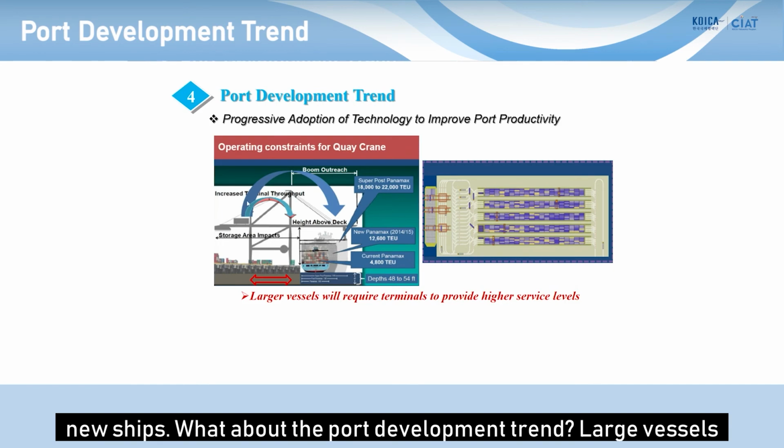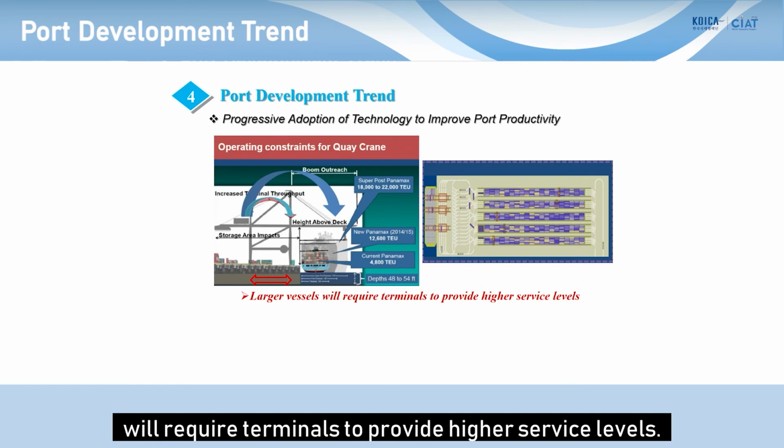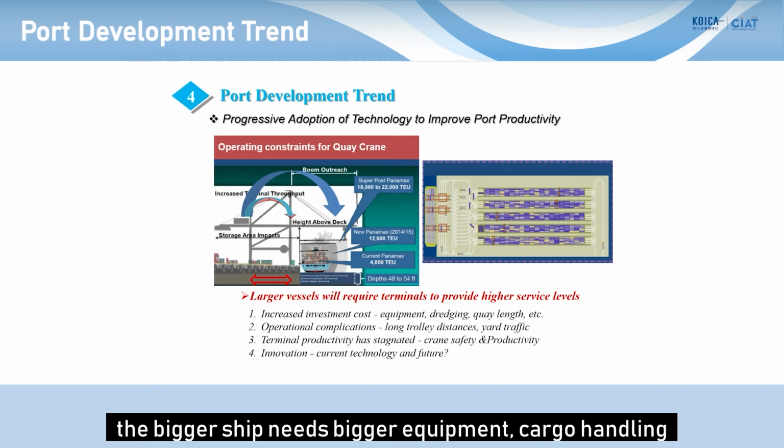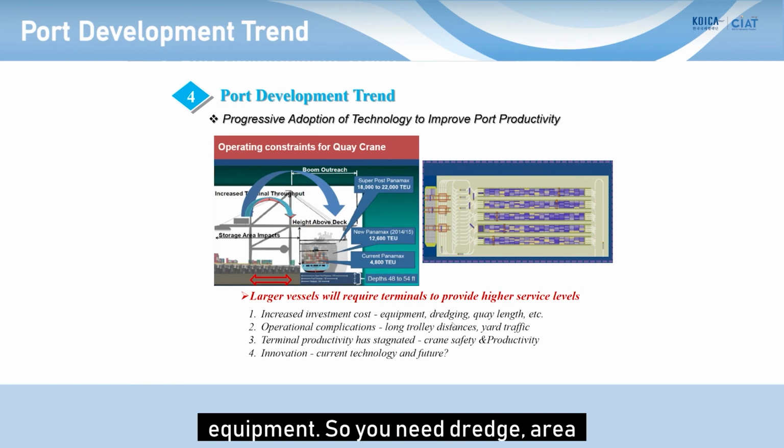What about the port development trend? The largest vessels will require terminals to provide higher service levels. The increased investment cost, because bigger ships need bigger equipment, cargo handling equipment. So you need dredging, mooring areas to serve bigger size ships, and also cargo handling gear, cranes. The reach of these is getting longer and longer. That means you need a bigger crane.